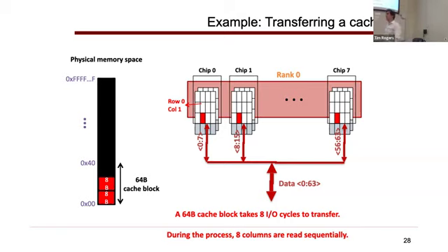And the upside of doing that is obviously you save energy because you don't have to cycle the whole clock to get the next one. It's a trade-off between do I make this clock faster or do I just read it on both edges? If you make it faster, then there's more transitions, so it costs you more power. If you just read it on both edges with a clock that's half the speed, then you're wasting less power in clock transitions. So I'm abstracting that away, but yes, you're right. If you're reading on both edges, it's going to take you 4 clock cycles to do this. Okay.